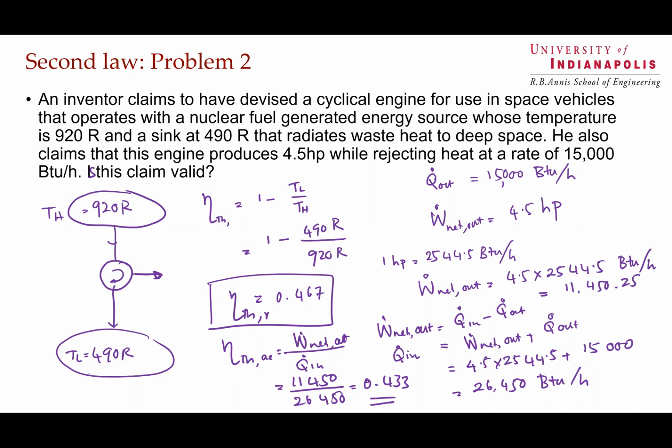So we can say that, I'm going to write it here on top because I'm running out of space. So the actual efficiency, eta thermal actual, is less than eta thermal reversible, theoretical. Therefore, the claim is valid. Okay. That's how you deal with that kind of problem.